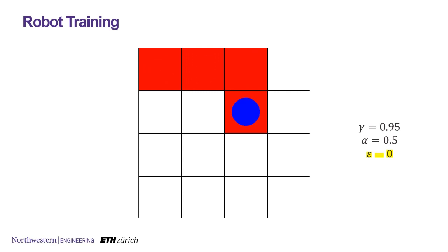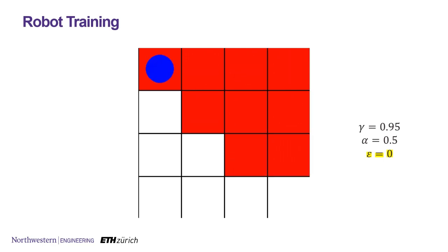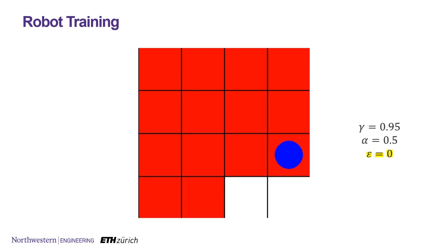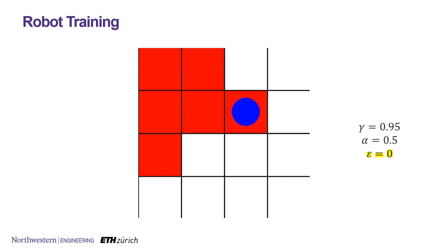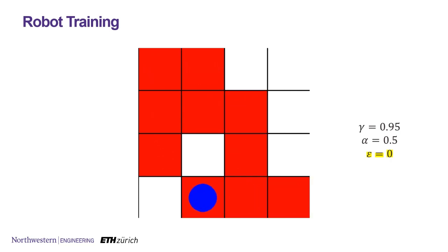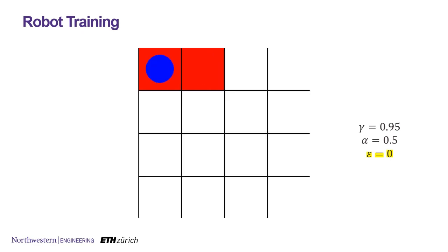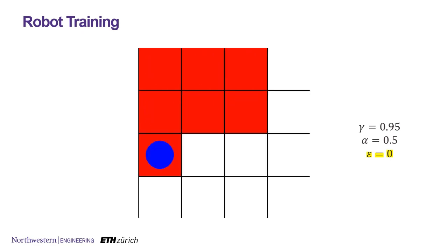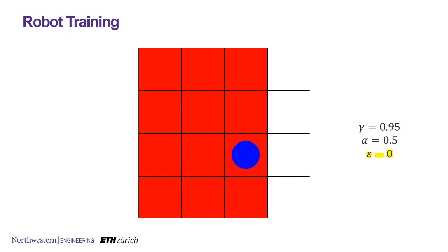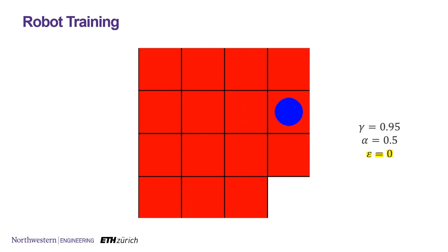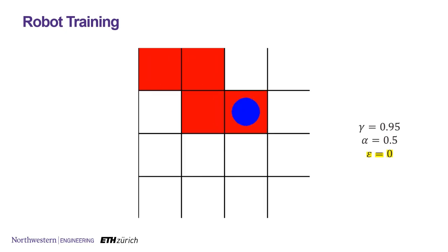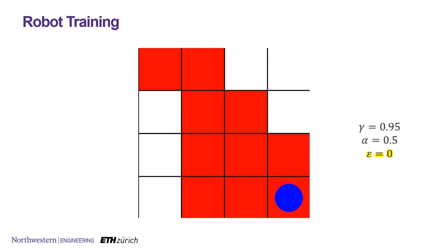This took quite some time to find out and figure out and control by adjusting the reward structure and the learning rate. Secondly, the robot is not actually improving quickly and does not seem to converge to a solution. Thirdly, and this is not visible here, the robot sometimes finds the optimal policy, but then leaves it again to pursue a suboptimal policy. In other words, the robot fails to converge in order to achieve a consistently high return.